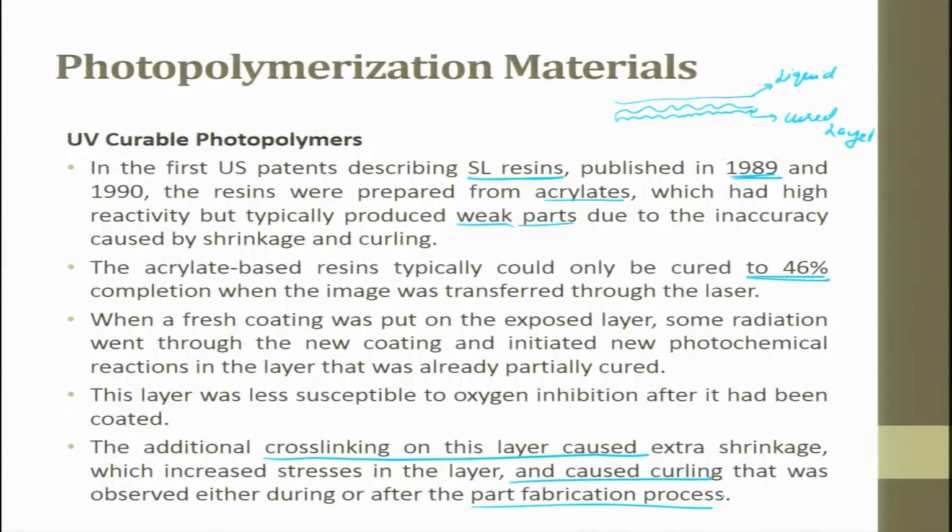So, once it is done, over a period of time the polymer starts curing. When it starts curing, it creates curling or warping and then delamination between the layers.